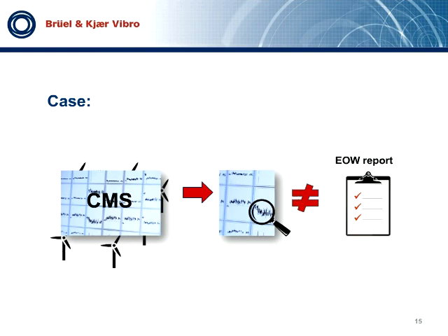And it became very clear that distinguishing between normal behavior and a possible fault condition is not something you find in your dictionary. But during that time, the data collected resulted in several up-tower repairs by the OM under warranty, which not only prevented major repairs, but also helped reduce unplanned downtime and thus loss of production. And as I said, lost production is often the greatest cost penalty of a wind turbine fault, and often the best argument for CMS.